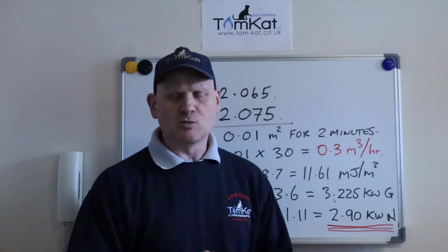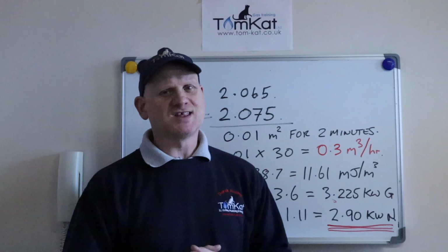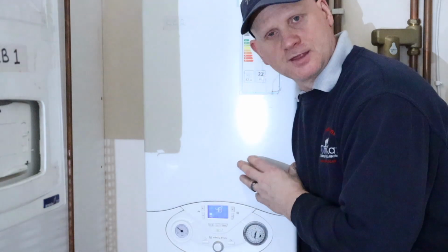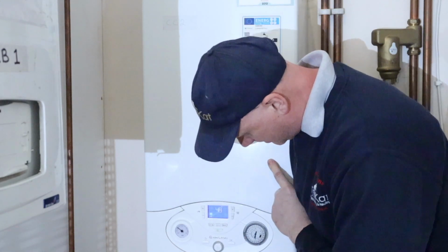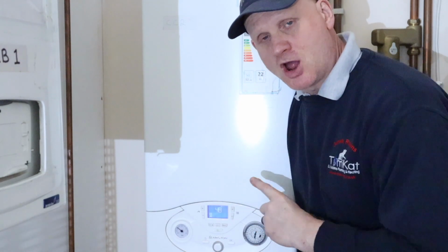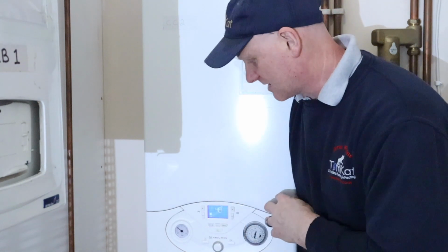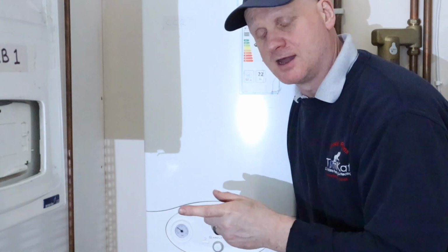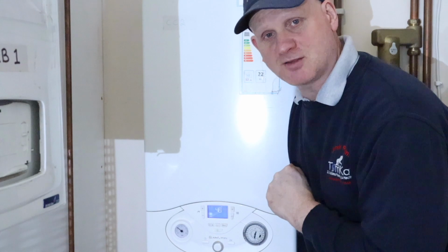What we're going to do is gas rate a boiler using a U6 meter, and we're going to see what we come up with there. This is the boiler we're going to be gas rating. This is the Ariston, it's an E-Combi Evo. So we're going to gas rate on hot water, because that's going to be giving us the maximum at this time of the year. So I'm going to get the tap on fully, and then get gas rating using this U6 gas meter.